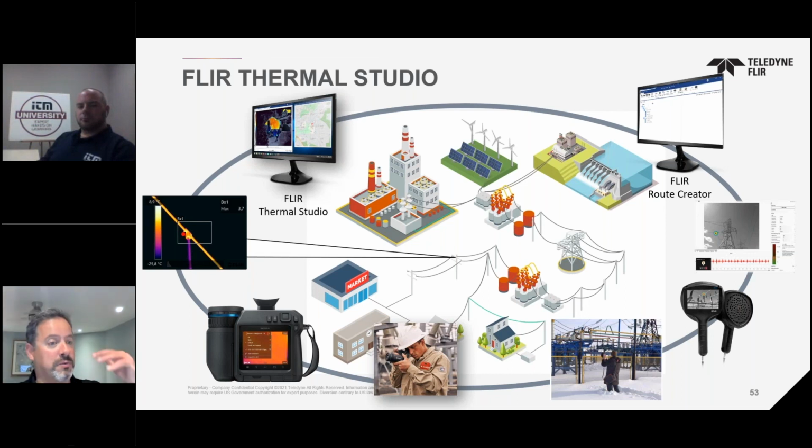So now the sun is giving so much energy, it's just capturing. And at nighttime, the sun goes down, and guess what it starts doing? It starts emitting that energy back, right? So we typically say for roof leaks to try and do it either early in the morning before the solar loading, or very late in the evening, after the surface has had a chance to get rid of whatever it absorbed to a certain degree. So late evening or early morning is the best time.